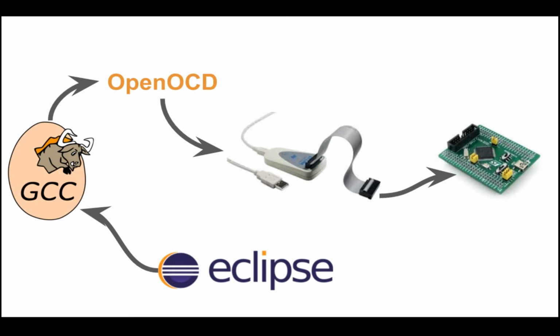And mostly, at least in this space, I've seen that the popular output format is a hex file, which is a hexadecimal representation of the binary, but with a little more semantics to it. So it is a little more human readable. So that's the output of this. Let's skip this guy for now. Once you have this hex file, you generally would use a programmer.